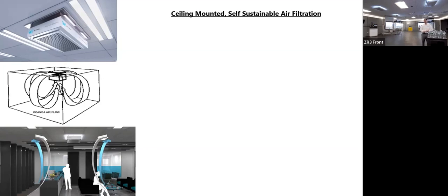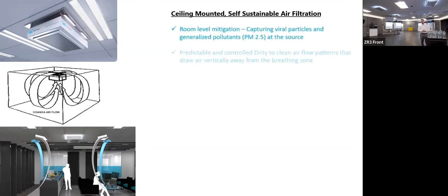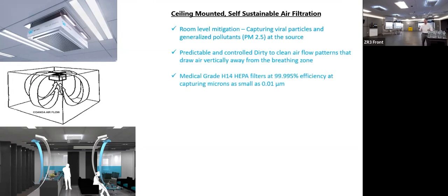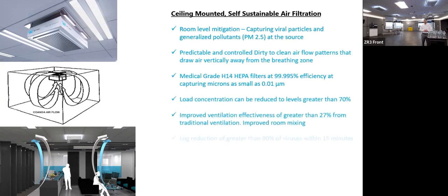We understand CFM. We know we can't just add 1,000 CFM because why? We're processing more air. No, we have to be cautious of proper diffusion, proper impaction when it comes to HEPA filter, and we have to understand proper residency time when it comes to carbon filtration. And again, airflow. We provide that Coanda airflow effect, which allows us to increase ventilation effectiveness, which I have third-party test data on as well. We can deliver to you upon request. Predictable airflow patterns is absolutely critical.